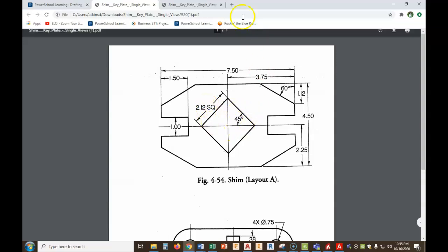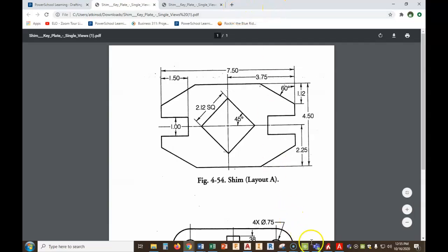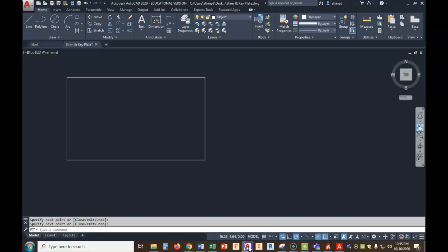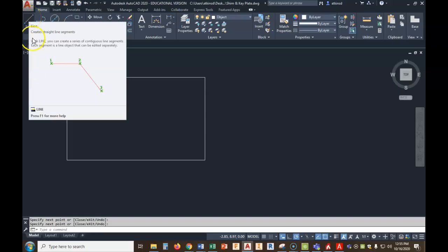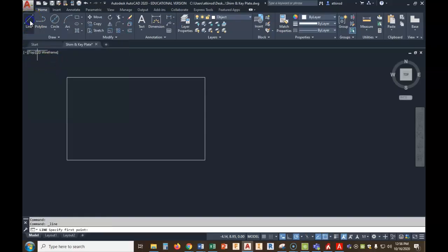Now notice this is laid over at 45 degrees. So I'm going to go back into our AutoCAD drawing. Okay? So I'm going to draw a square, and I'm going to draw it dead center of this object. I want to go ahead and do that. So I'm going to go to line. I'm going to hover here and drag across. Notice my green line. Now I'm going to find my midpoint here, and I'm going to drag up. I still have not clicked. All of a sudden, boom, look what it found. It found my midpoint right here.